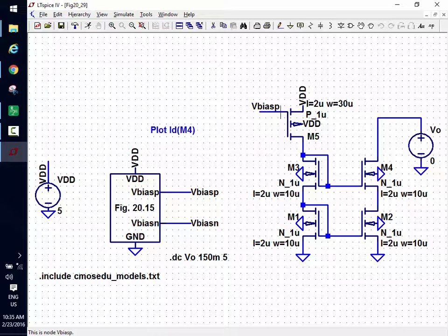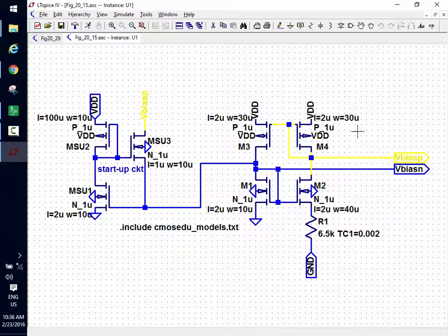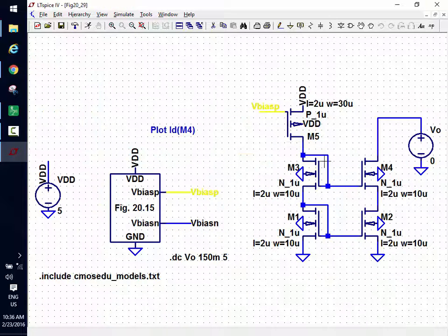Just to make sure, because I'm used to looking at circuitry, if I ask what's connected to this node here, what sets the current here? Yeah, it's a gate voltage. It's a gate drain connected PMOS. I push down in here. There's my gate drain connected PMOS. That's how I'm getting the mirror out. Does everybody see that? Same old thing. Current mirror, gate drain connected. So I go over here, and then I've got my 2 transistors. I've got my cascode structure here.